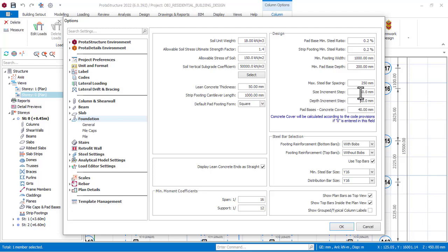All right. Okay, so right now on this place that says cover, for foundation, you can use a minimum of 40 or 50, while US ACI uses 75 and 100 as their cover of concrete for foundation. So right now the software gave me 40, which is the minimum, but I'm going to use 50 because 50 is the most common, and it will be very easy to measure 50 at site when you're using the tape. So that's why I'm using 50 millimeter.